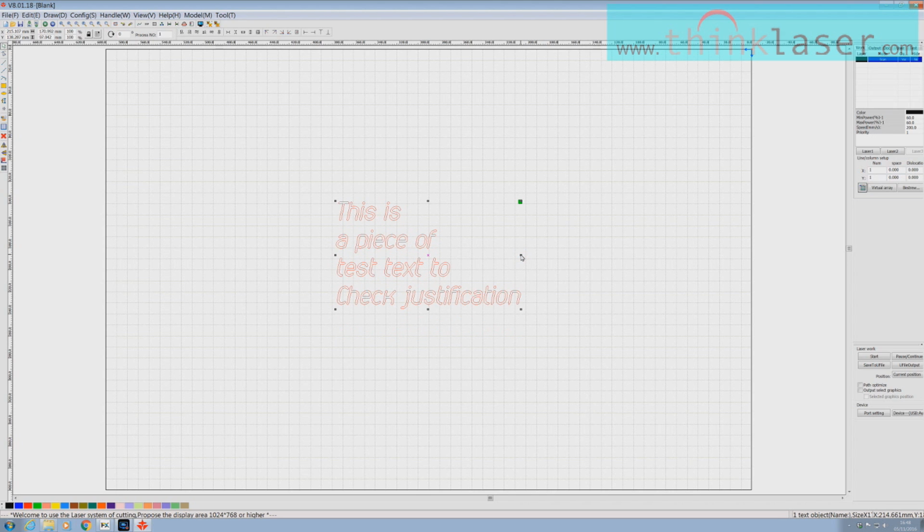Now there's something else that you might be interested in. Just put some handles on it, and if I grab hold of this side handle, I can mirror it. But of course it isn't mirrored to any special extent because I may have got it incorrect when I stretched it. It's a freehand stretch which reverses the text. So let's just undo that, Control Z, because if you do really want reverse text, you've got a feature here, horizontal mirror, which will achieve the same thing for you perfectly.